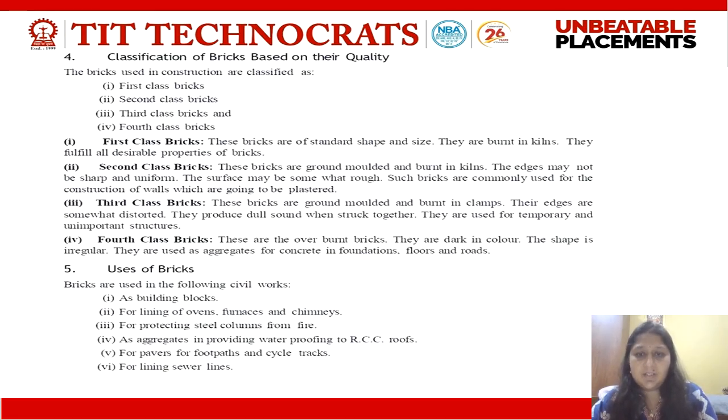The third class bricks are ground molded and burned in clamps. Their edges are somewhat distorted. They are not proper edges. They don't give me a good sound. They give me a dull sound when struck with each other. Hence, they are used for temporary and unimportant structures.